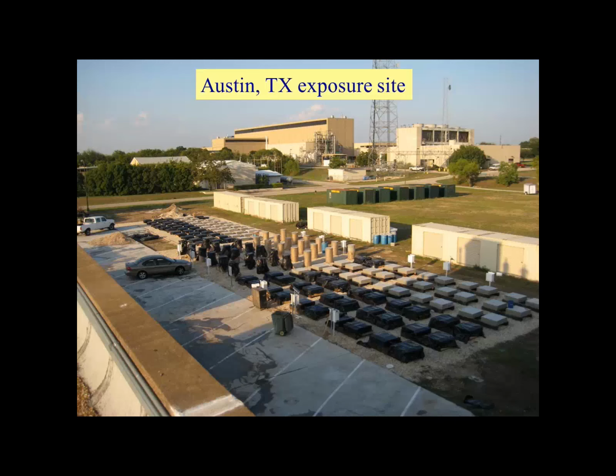And so one question that may arise from that kind of experience is that if you were able to drive lithium into the concrete, as Kevin explained, would the amount of lithium that you drove into the concrete be enough with the particular aggregate that you have in the concrete?